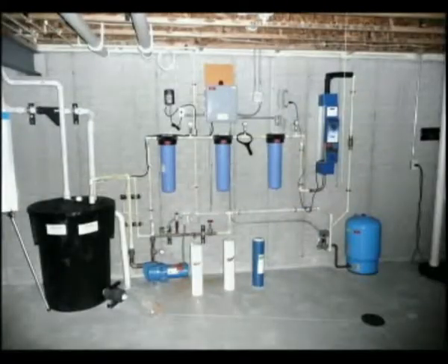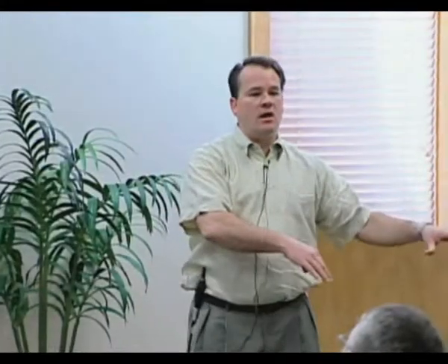So what we've done here, in the basement of the Trend Home, is take our shower water and bring it down into this 75-gallon drum. Then we recirculate the water through this filtration process, the first filter, secondary, and our third one, before we get to our UV light filtration system. Once it's clean, it comes down into a pressurized tank, and when we flush the toilet, the water system calls for this water and pumps it back up into the toilet. We use that water again before it goes down into the sanitation system. So we're using it twice.